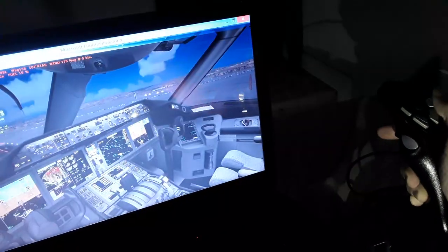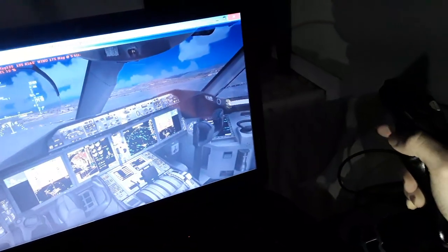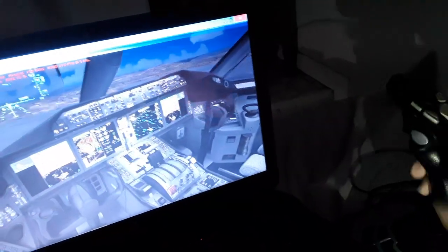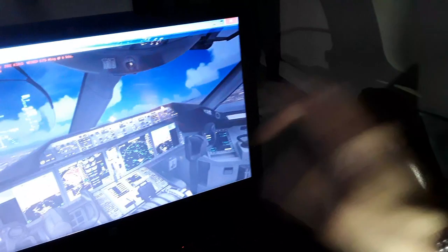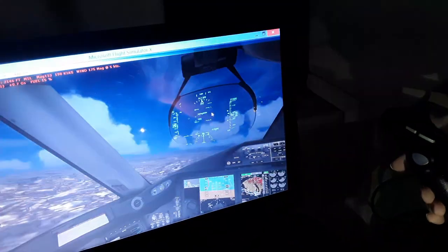We do the same for landing. Use a small pitch attitude, less than 9 or 10 degrees. So we keep climbing. Over here pitch trim a little bit up, also flaps, maybe less flaps over here.